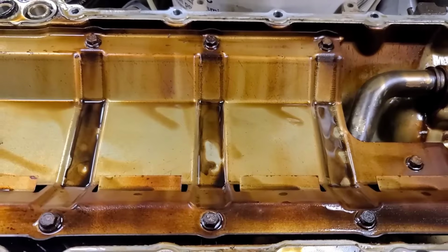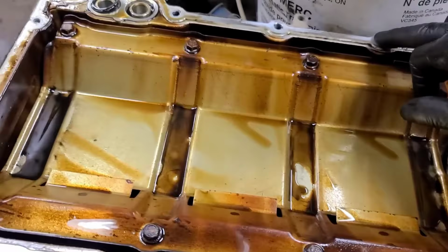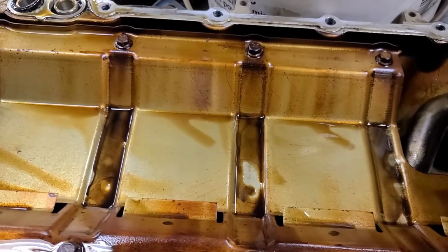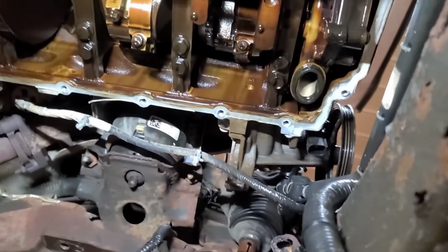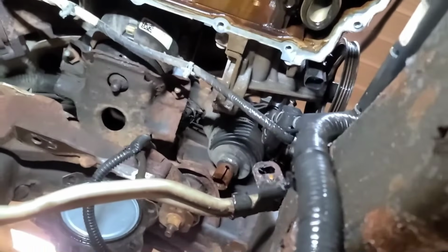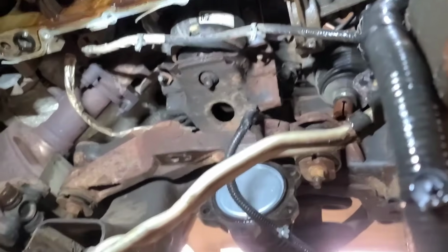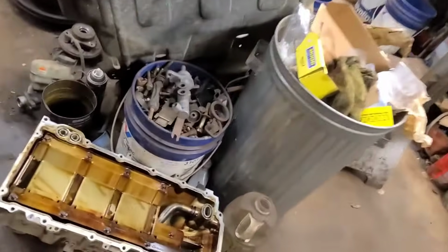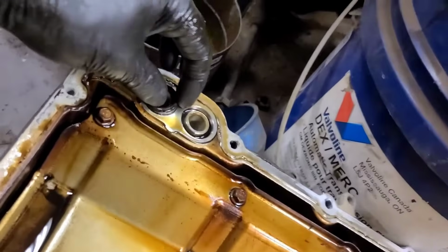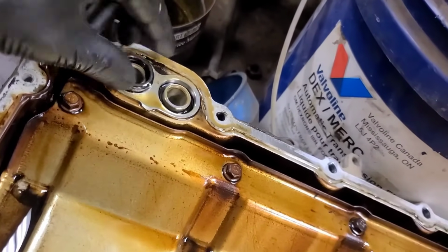There's a couple of dowels. I see one dowel has stayed here in the pan, so that means the other dowel is over here, probably, no, maybe right here in the block. Let's have a look up here. I don't see a dowel on that side. A couple of O-rings back here where the oil filter housing goes on. Those are important O-rings. Yeah, these 2 O-rings here. Make sure we got new O-rings for that.